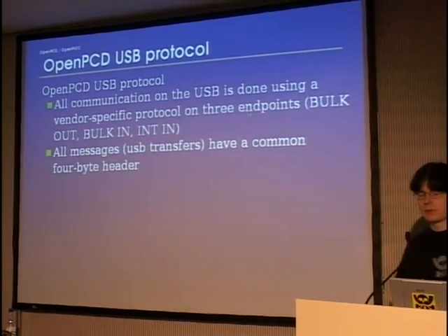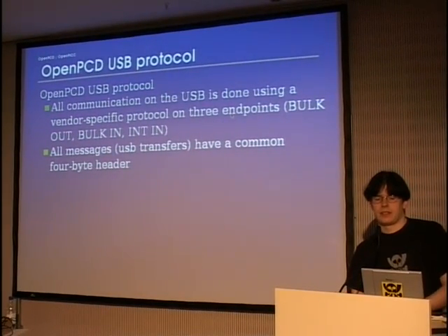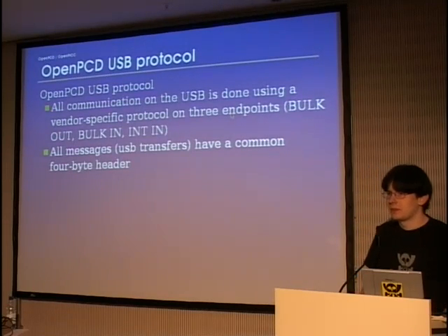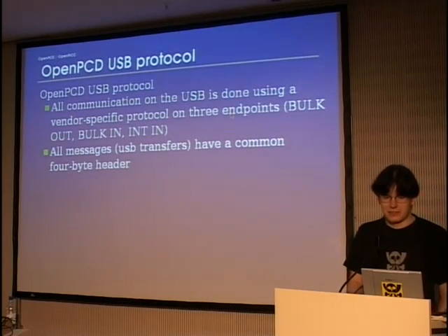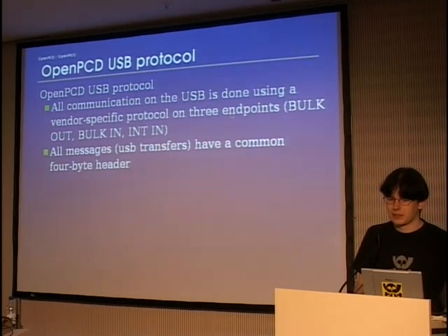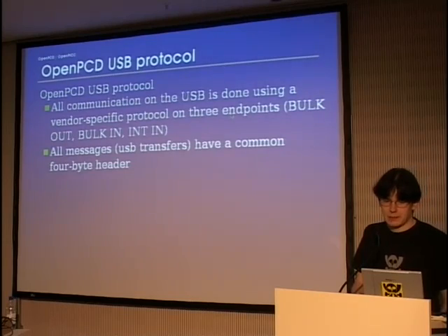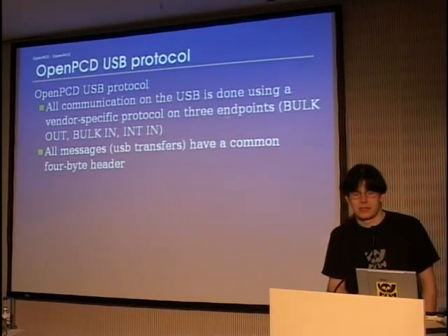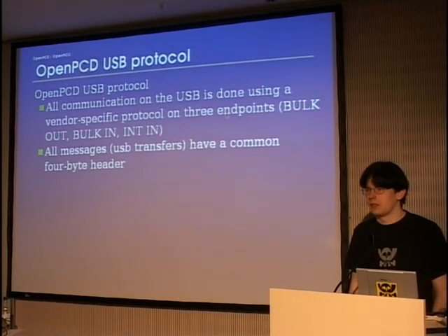So the USB protocol that the firmware talks to the host is using a vendor-specific protocol, so it's not like trying to be a human input device if it isn't one, or trying to be a serial device if it isn't one, but rather it's a vendor-specific protocol. It has 3 endpoints. Unfortunately, we cannot have more endpoints. That's the restriction of the hardware. But we can work around that. So we have a bulk in, bulk out, and an interrupt in endpoint, and all messages, the USB transfers have a common 4-byte header.